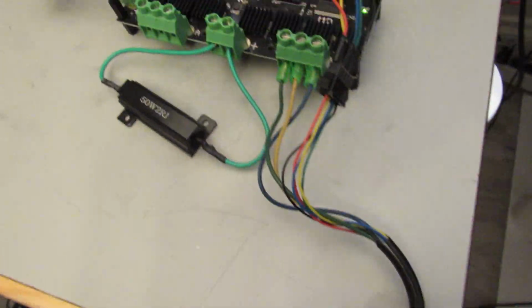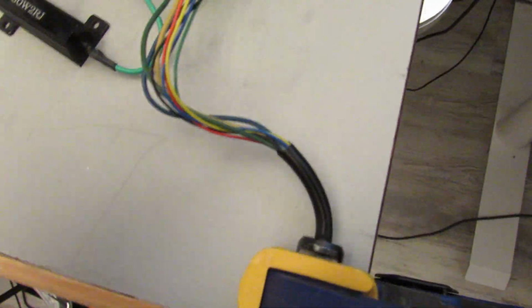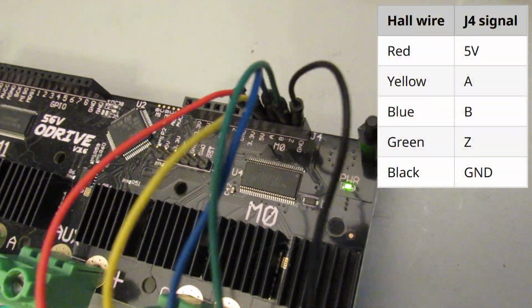Connecting the motor to the board is very easy. You can plug the motor phases in any way that you want. I currently have the phases plugged into channel 0. The encoder signals coming out of the hoverboard motor are color-coded. Here's a pinout for what colors go where on the board.